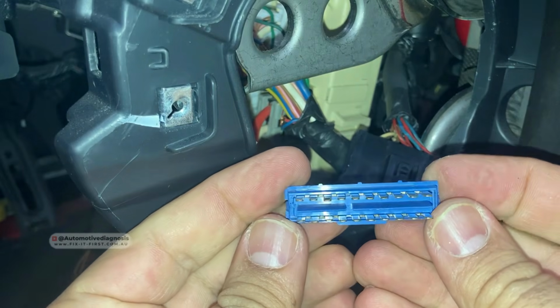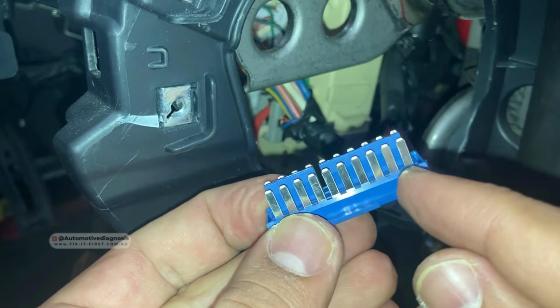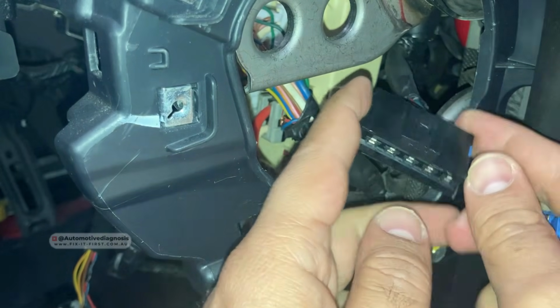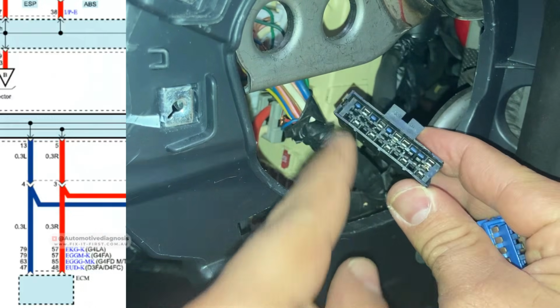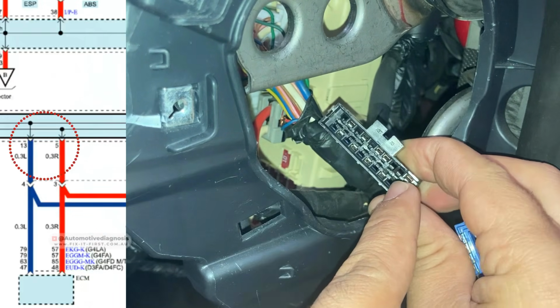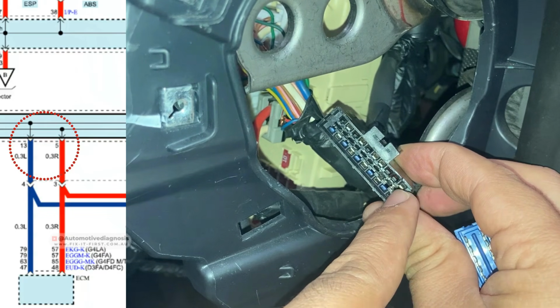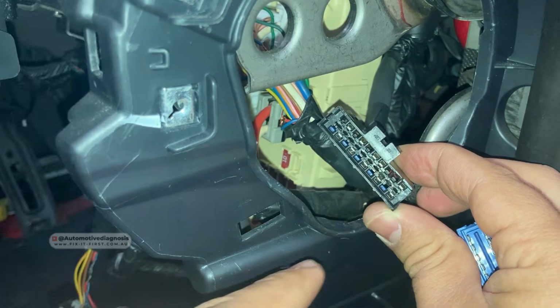This is the joint connector. So these pins are connected to each other from here to this point and from here to this point. Right now that we remove the joint connector, we can check the pins one by one from here. For example, if you find the CAN bus high and CAN bus low for engine control module here, you can actually check each wire from here, and that's going to be the network wiring of the ECM. I'm going to put this one back.